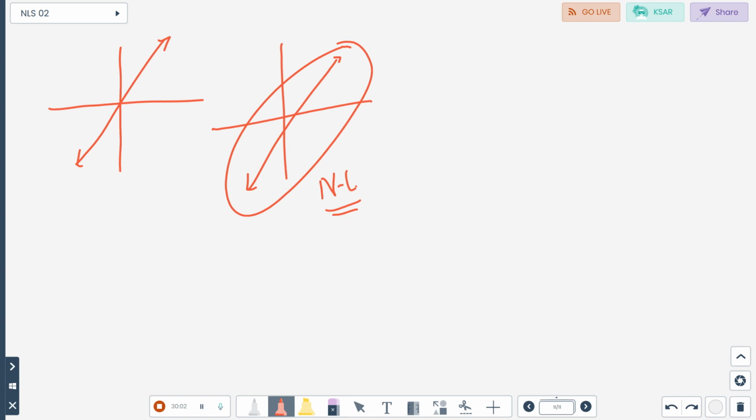So this second curve here represents the behavior of a nonlinear system, not that of a linear system. Even if the output is varying linearly with respect to the input, because of that shift in the origin point, this becomes a part of a backlash nonlinearity, and there is a hint of nonlinearity in this system that is enough for us to classify this as a characteristic of a nonlinear system.